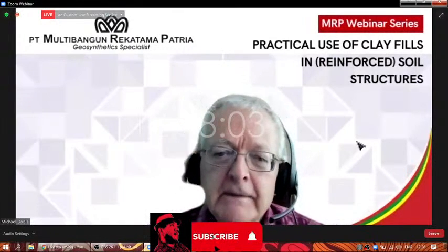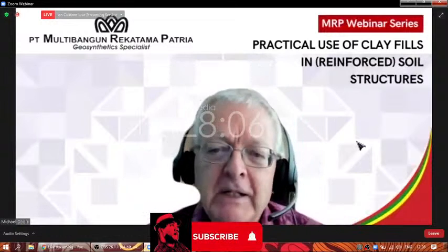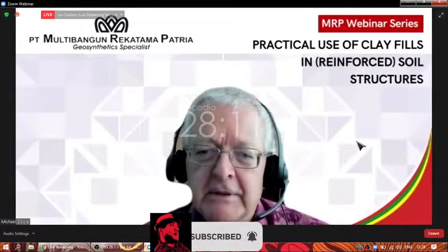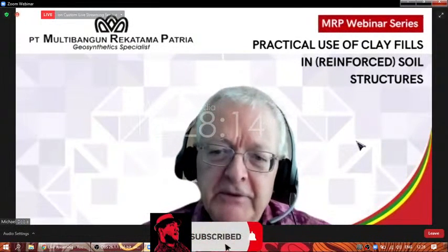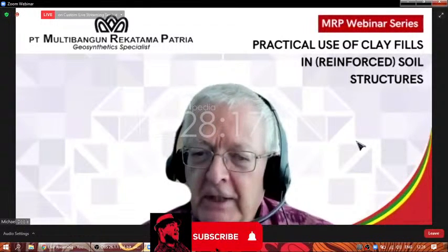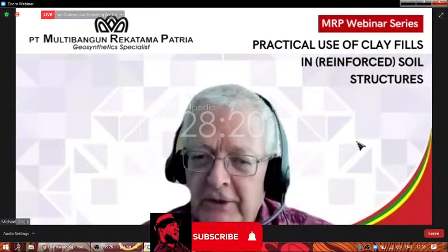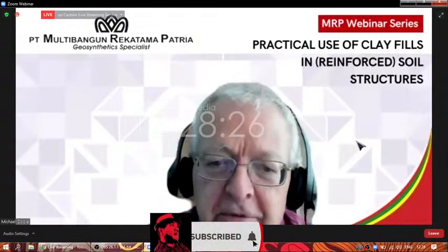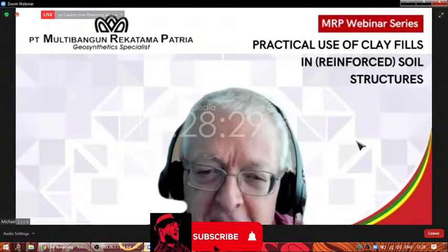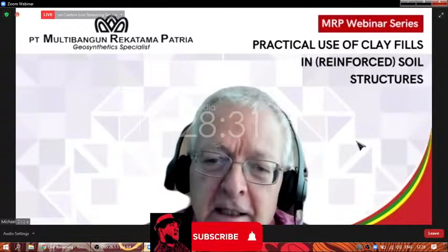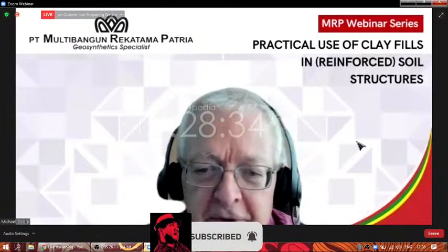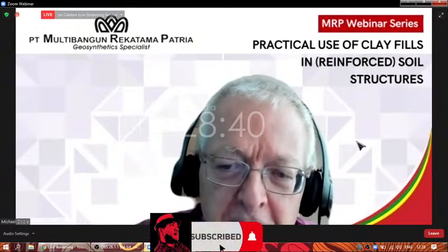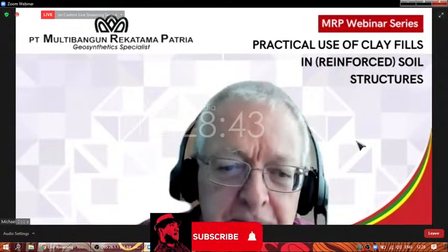However, as clay permeability reduces, it's likely to be a bigger content of the finer clay minerals, which means it may have a bigger tendency to crack. And of course, if it cracks on drying, then water runs in through the cracks. It doesn't run in through the clays. So yes, that can be a negative issue of very low permeability clays: to be very, very low permeability, they may have clay minerals that you'd rather not have. Some of the smectites, the montmorillonites, may have a higher content, and therefore be a bit of an issue.